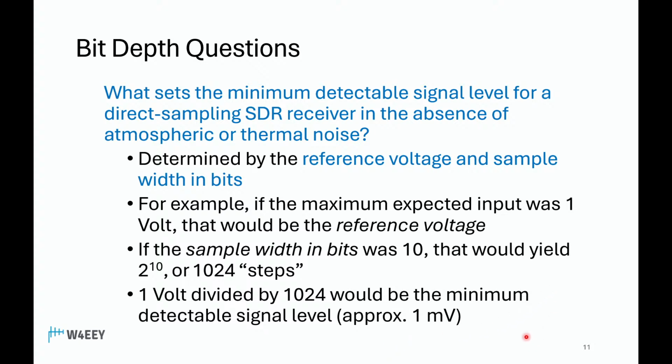And you may have noticed, if you've got an SDR, that occasionally the OVR light might come on if there's a lot of strong signals. That's the overflow light, meaning that there's too much RF coming into the front of your radio and it can't handle it all. So in that case, you would have to crank in some attenuation. I've very rarely seen this on my radio, but it does happen.